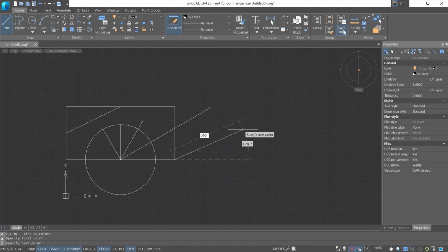You can enter it manually on the keyboard. And accordingly the displacement angle. Let's press tab. Let's put it 35. You see that it is also highlighted by polar tracking. We won't go into detail about it now. We'll cover it in the next lessons.